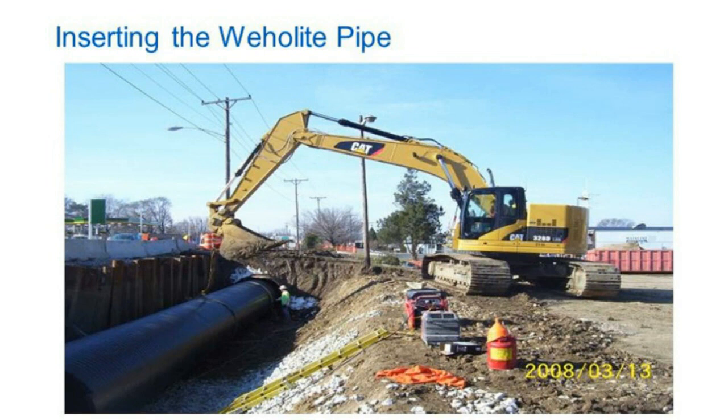And once they can continue to do that, then they're just going to repeat this process, inserting the pipe, leaving about 25% of the pipe out of the host pipe, and then bringing the next section of pipe in. There's several different ways to insert the pipe into the host pipe, which you're going to see here in the next few slides and portion of the presentation here.